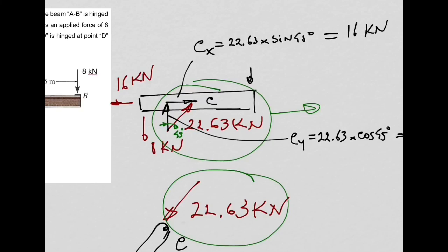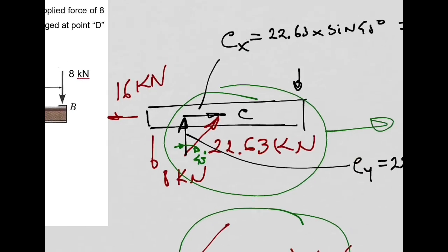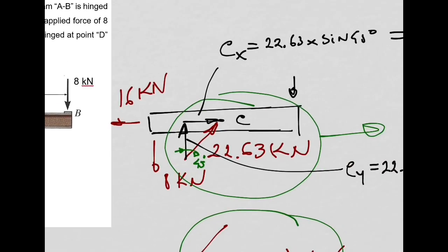What external forces are you using? So you have the force of 16 kilonewtons to the left, and you've got 16 going in the vertical direction also. These two here in black, right? The last one in red. Right. So the red is the reaction of the strut into the beam. So instead of using the force, can you just use the external forces to give your reactions? Oh, okay, I know what you mean. These 8 kilonewtons. Yeah, you go there. Give me the same answer.